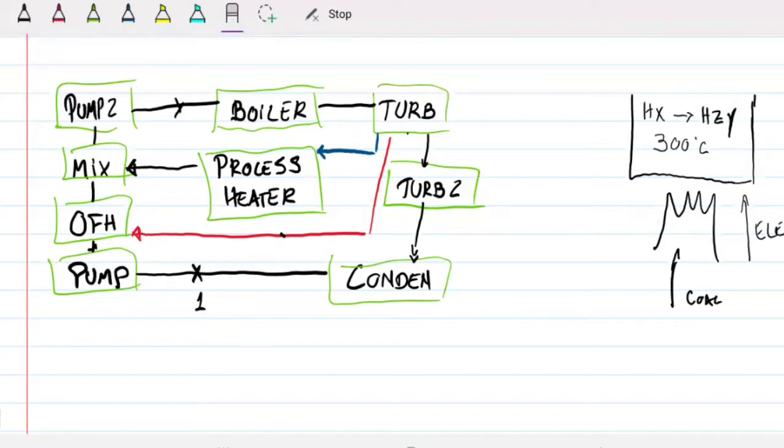So if I'm going to input a lot of energy here, so much so that it might be worth building a power plant, either combined with my own or by making a partnership with a company that operates power plants to build one right next to my system. Once that hot water leaves the turbine, which is this point here, I can have pipes that go through my system, and the water is just going through. It's not touching the chemical or anything like that. It's just going through so that I can increase the temperature of this here. So I can take this to 300 Celsius.